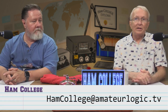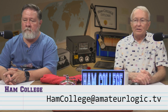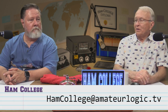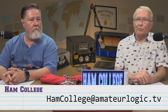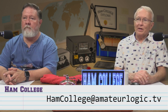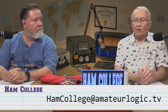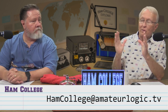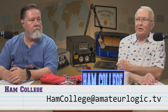Well, I haven't lately, but I have worked AM a number of times, and to me it's nostalgic because I worked in AM radio when I was 16, and I used to do a lot of DX and still do some DXing on the AM broadcast band. There's something about the sound of AM. It's a lot different than sideband. Yeah, your signal is going to go further with the same amount of power on single sideband because you've concentrated it all into just one sideband. But AM has a certain characteristic sound, a little higher quality.